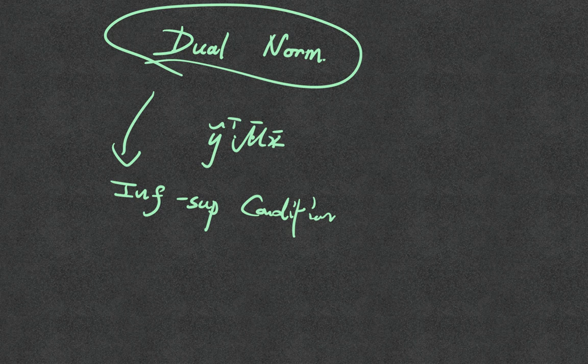And of course, there are more variations we want to cover for the rest of the course, like multi-phase flow. How do we deal with the case where we have a retention curve with air or other things, or materials that are freezing, or dynamic problems where we want to propagate a wave, which would also be of interest. But I think from the mathematical side, knowing the inf-sup is crucial for formulating a stable mixed finite element. If you don't do anything, maybe you can solve the problem, but you cannot reliably solve it. In fact, if you use equal order finite elements and a very big time step, sometimes you don't have any problem. But then your solution would not be robust.